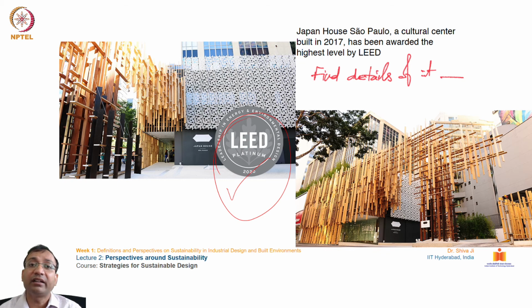First of all, it's creating an air buffer. I'm sure you can understand that. By this crisscrossing, puzzle-like structure, it's trapping air, restricting the air movement on the surface of this building. And air is an insulator material.